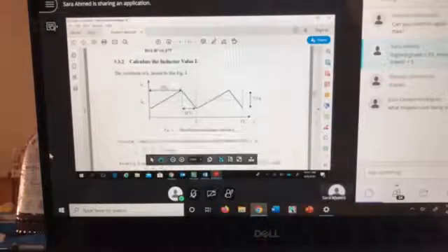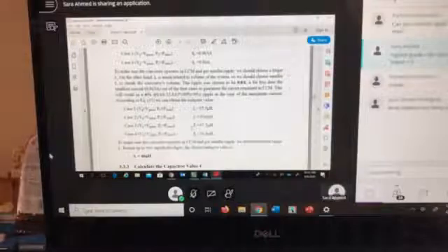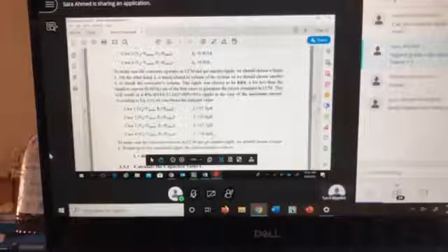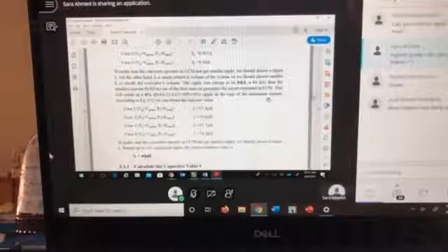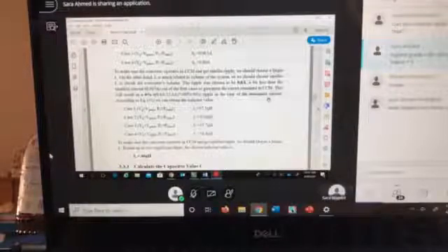So I calculated 4 inductance values, like you see in here, these L's, and they are all pretty much close to each other. They don't have to be close. We'll see in the capacitance, they will not be close. But in this case, they came up to be close. But then what? Am I going to be changing the inductance every time I'm running my simulation? No. Why? Because in the hardware, you're not going to build a converter with 4 inductances and it's plug and play. It's 1 inductance has to fit all.